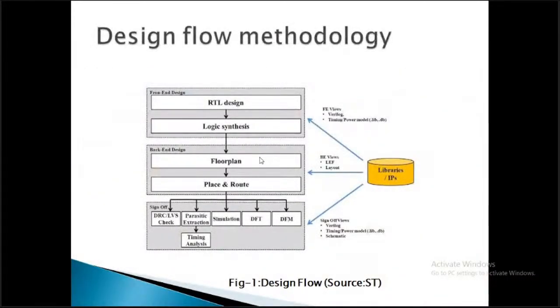So all these things are done through a proper methodology. That is what we have done right now. First we have done RTL design, then we go for logic synthesis, floor plan, placement, routing, then we check DRC, LVS, we did parasitic extraction, actual delay analysis, simulation. Then we put some testability as well, design for testability, some flops, scan chain we used to put in our circuit, so that after fabrication we can check whether our chip is working properly or not.